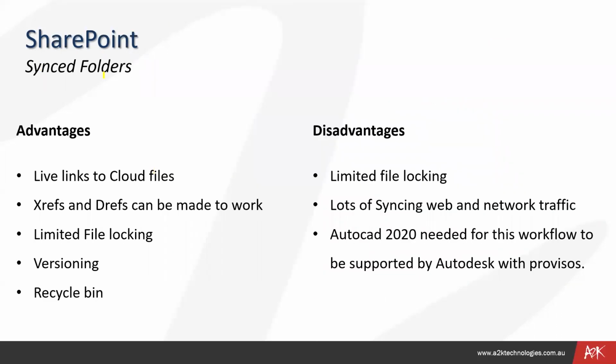So the advantages of SharePoint synced folders is that they are live links to the cloud files. The Xrefs do work, as opposed to directly just downloading a drawing from the cloud. You won't have those. There is limited file locking, just be careful about it. But we do have the nice versioning, and we do have the recycle bin if things get accidentally deleted.